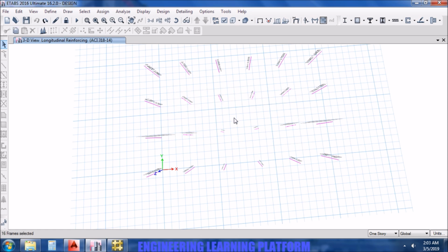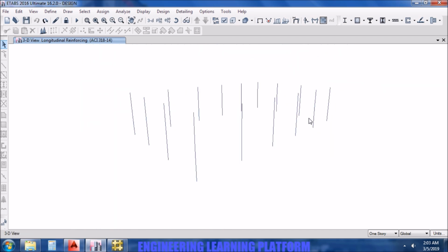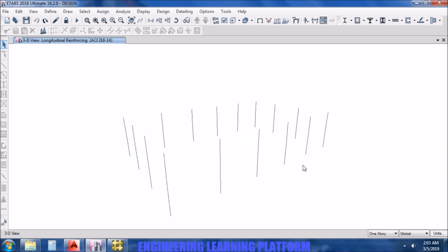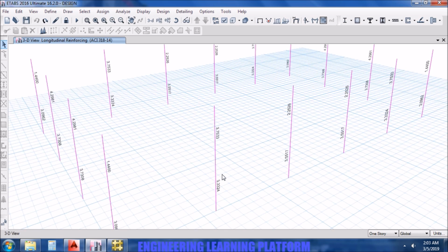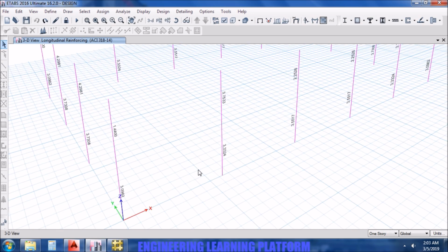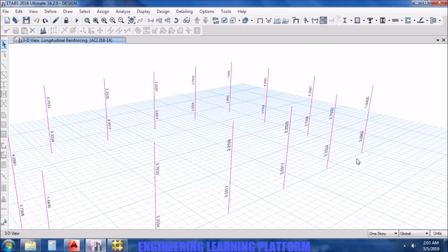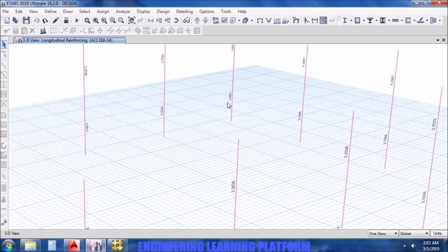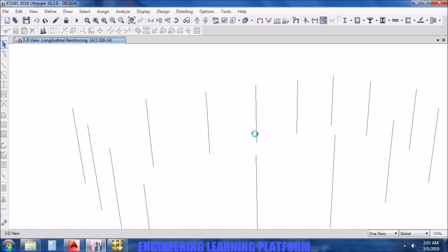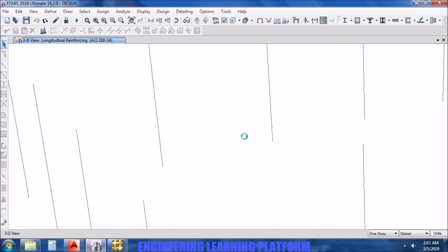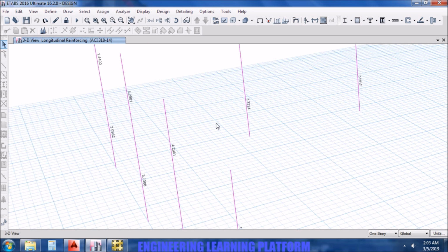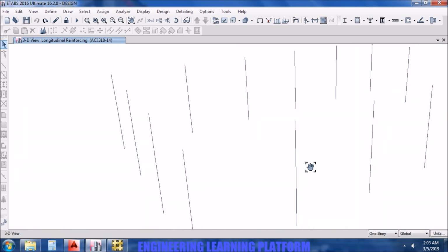So from design point of view, we will be putting the higher steel, whether it's coming from the above story or the lower story, inside the column cross section of the bottom story. We need the area of steel in terms of percentage usually. So in each and every column, the higher value will be governing for all of the columns.